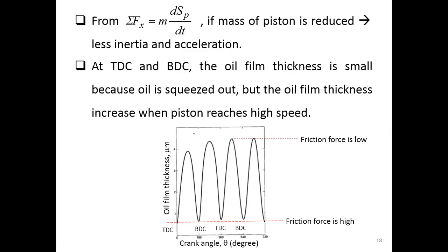Okay. Another thing that we should notice is in this picture, which shows the oil film thickness along with the crank angle. From this picture, you should notice that at the top dead center and at the bottom dead center, the oil film thickness is smallest, or very small.